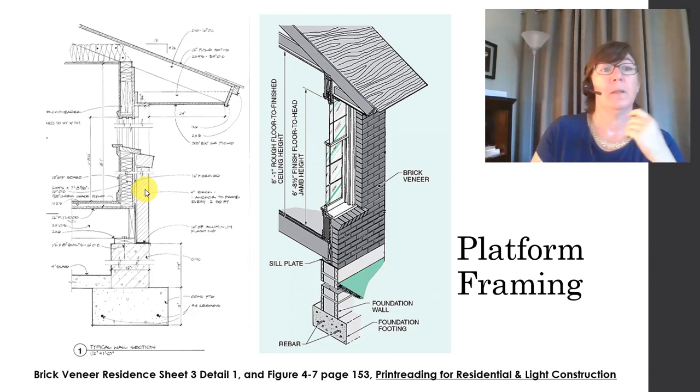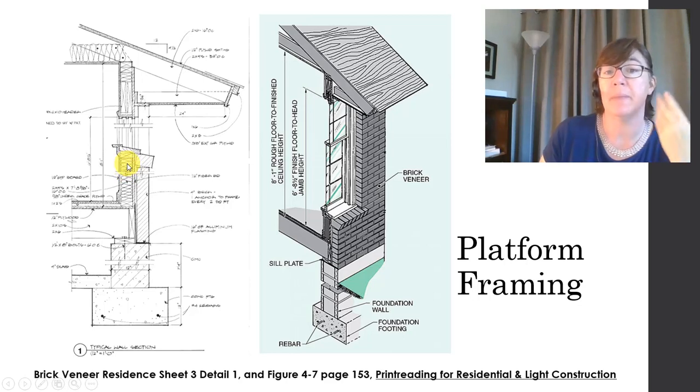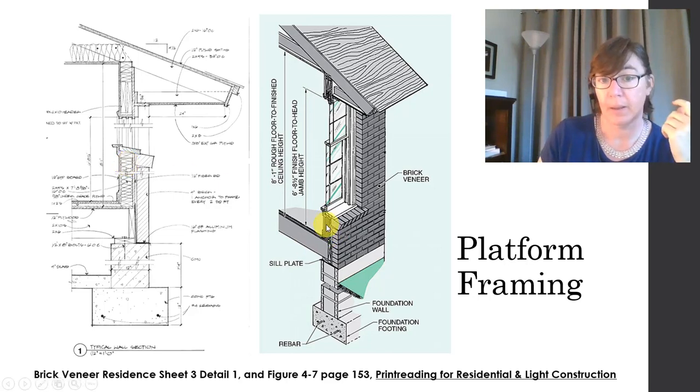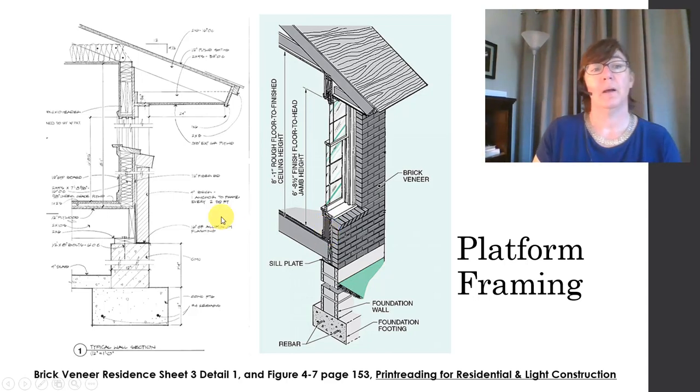All right. So here is our wall right there. This little S-shaped back and forth symbol is showing the insulation in that cavity of the wall. Okay. So right here, we're seeing the wall, and that's the studs going vertically. On the exterior, so there's a small gap. Here's our sheathing, which says it's a 1/2-inch fiberboard right there.